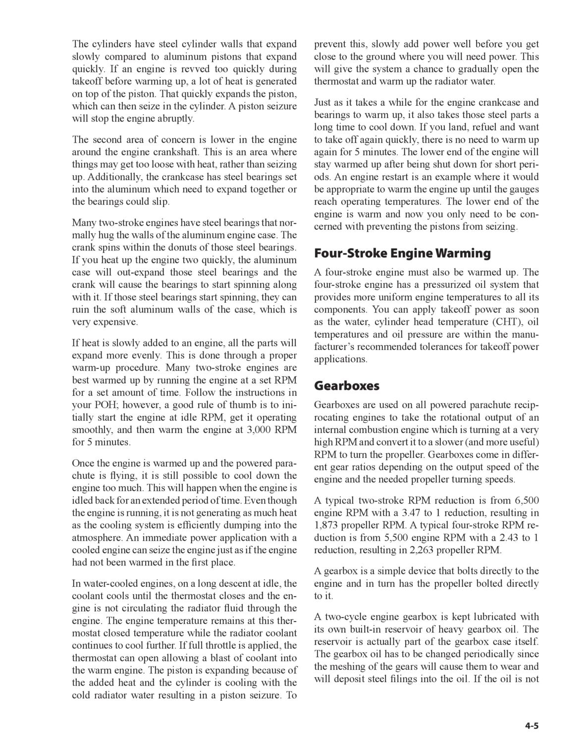You can apply takeoff power as soon as the water, cylinder head temperature (CHT), oil temperatures and oil pressure are within the manufacturer's recommended tolerances for takeoff power applications. Gearboxes are used on all powered parachute reciprocating engines to take the rotational output of an internal combustion engine, which is turning at a very high RPM, and convert it to a slower, and more useful, RPM to turn the